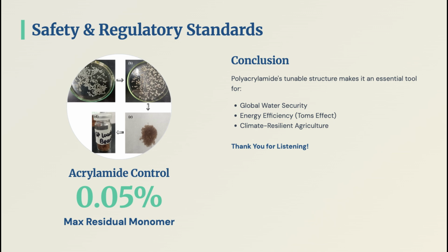Executing this effectively requires a precise matching of the polymer traits with the water chemistry, the mechanical shear environment, and the structural constraints of the process. And remember, always validate these molecular dynamics through laboratory jar tests or pilot scale evaluations before advancing to full-scale operations.